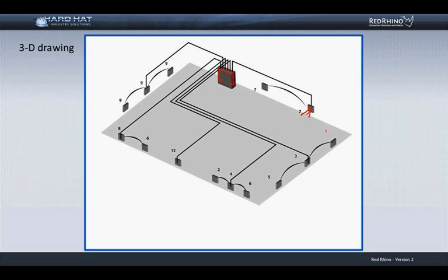At the junction boxes, the wire must extend out far enough to make up the devices. In electrical panels, the makeup should be about 3 feet, at junction boxes about 1 foot. To calculate the wire makeup length, you use the average length of both ends, so in this example, we would set our makeup at 2 feet.